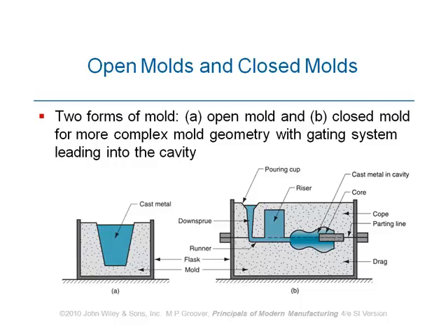What's the role of the riser? Does anyone know? Yeah? Because the mold flow is very up and down, and then growing the mold. For this reason, we put the riser. Indeed, the mold flow becomes slower. You mean turbulence, right? Yes. If you are referring to turbulence, it's the pouring cup which is taking care of turbulence and lowers the turbulence as much as possible. That's why we have got the pouring cup here, in order to lower the negative effect of turbulence when we are filling in the cavity.